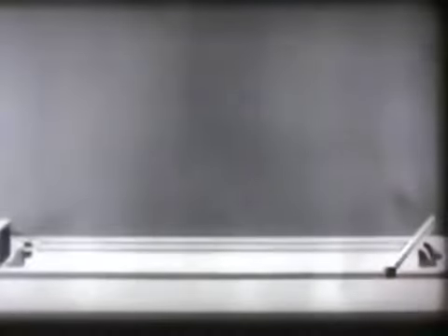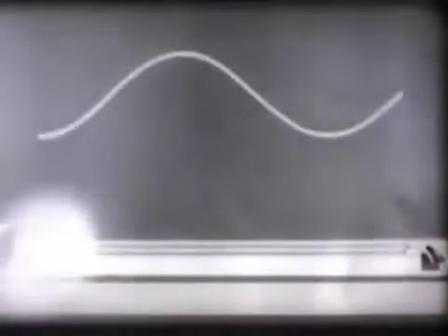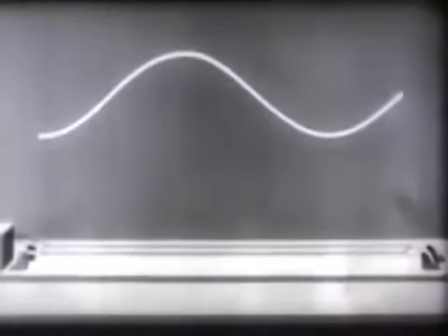Now here's another phenomenon of resonant transmission lines. When an ordinary fluorescent lamp is placed near the line, it can be used as a voltage indicator. When the tube glows the brightest, it indicates a point of peak voltage in the line. A voltage plot of this line would look like this.